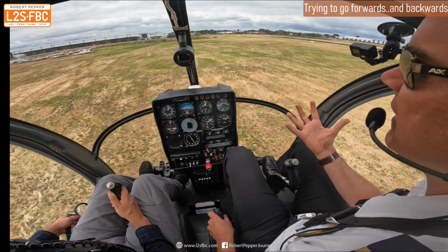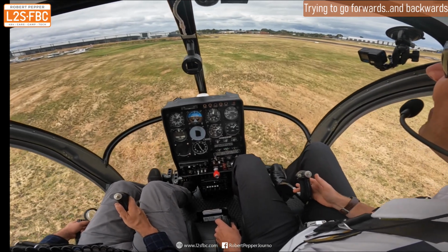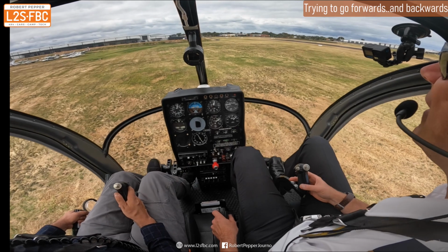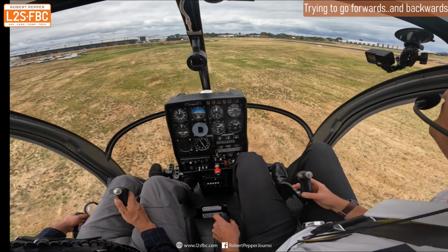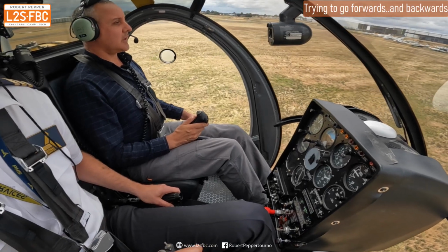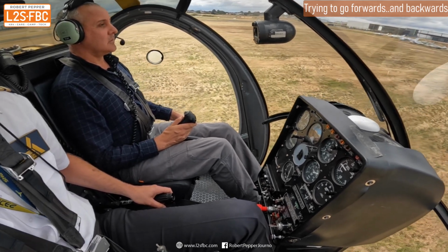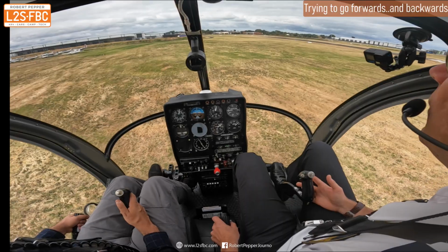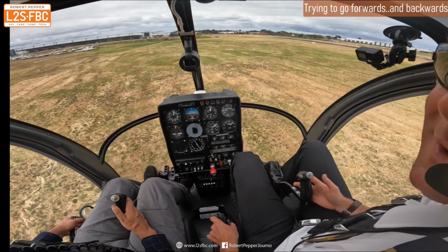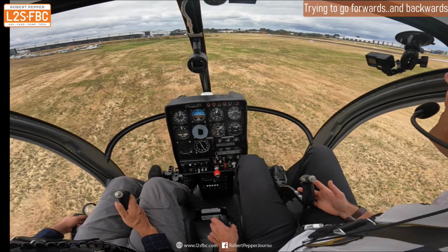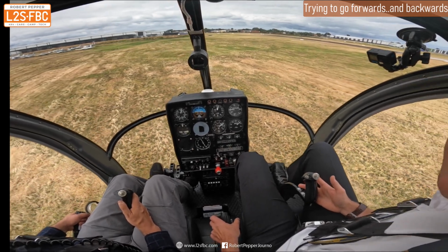And then I thought, okay, let's try and fly a helicopter backwards. And that's pretty exciting. So here we go. And into a hover-ish, my version of a hover, we just pull the cyclic back just a fraction, and again we just wait, you know, it's not instant, and then look, we're going backwards. I'm flying a helicopter backwards. This is one of the greatest days of my life. It's just awesome.